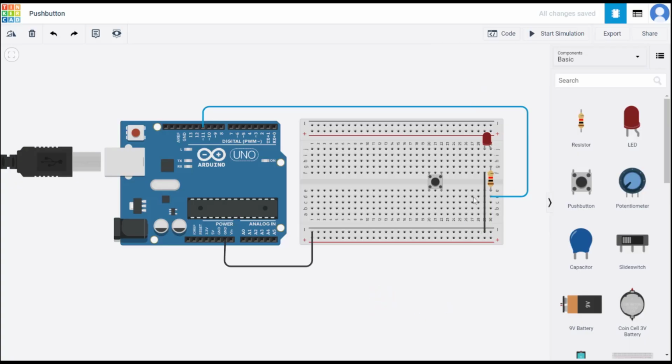All right. Now this circuit is complete. The next step I need to do is make this independent circuit of push button, where we need one side of the push button to be connected to plus 5 volts. So let me take this and let it go all the way to plus 5 volt. Let's take this as red.